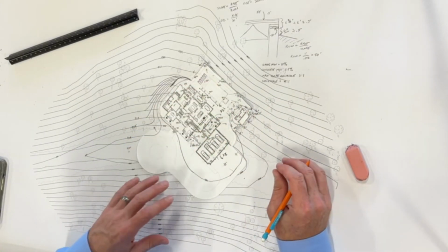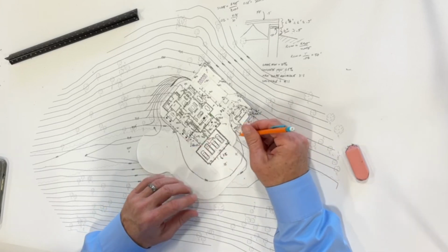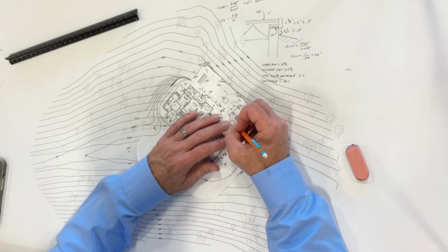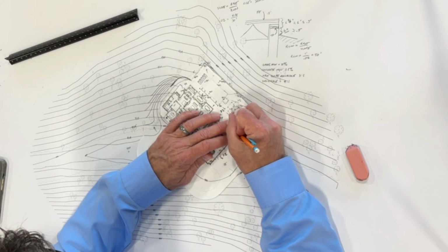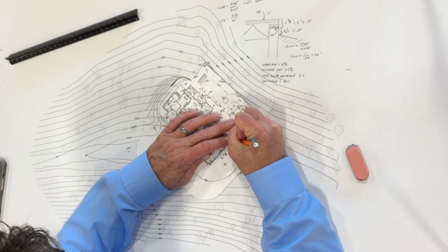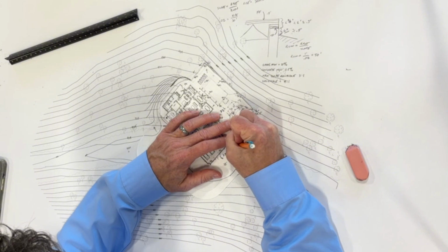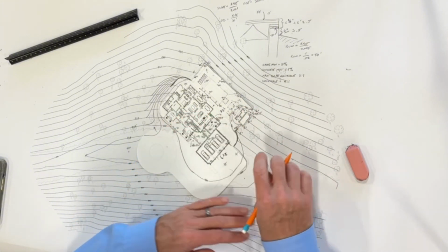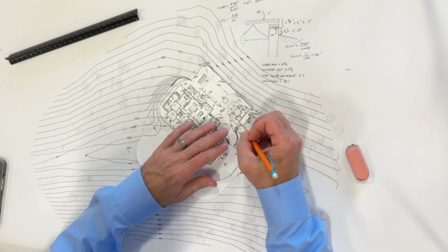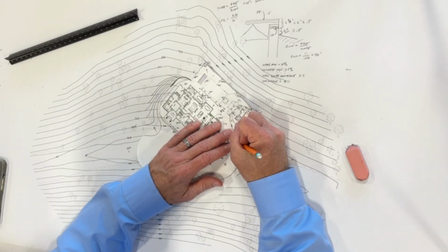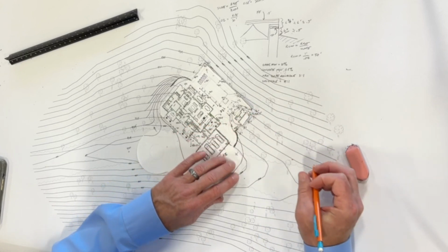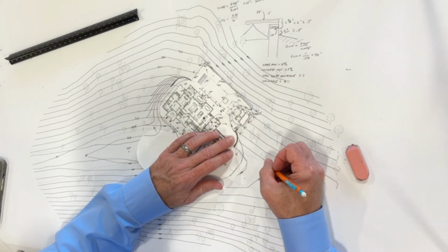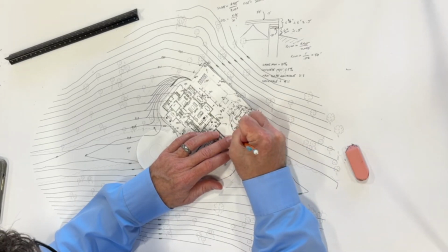Okay, now let's see what's happening here. So now we got a 940, but that's a 934, so it's still a 6 foot drop. So what that means is this retaining wall is actually going to have to come like this around. Otherwise, we're going to have to come too far down the hill. So now by making this retaining wall this way, we can have, let's see, a 940. So that's a 935. So that's a 5 foot wall.